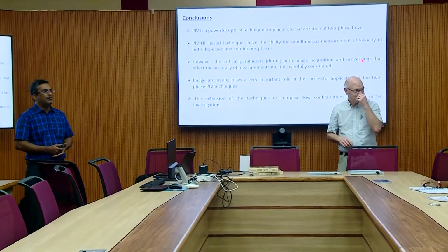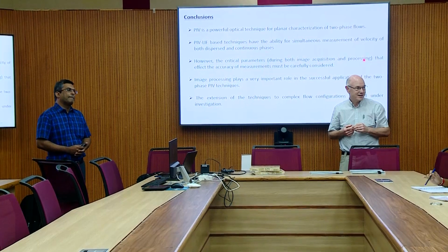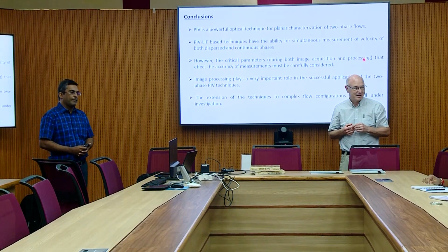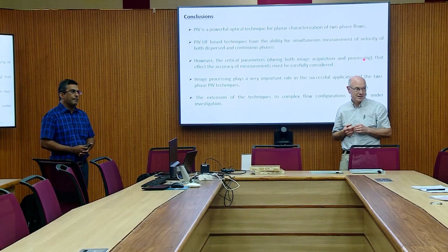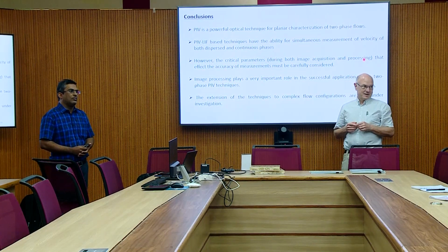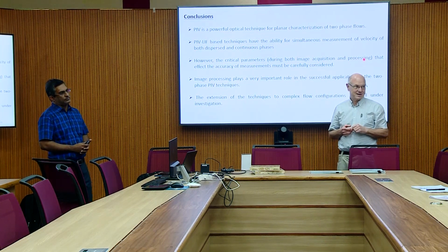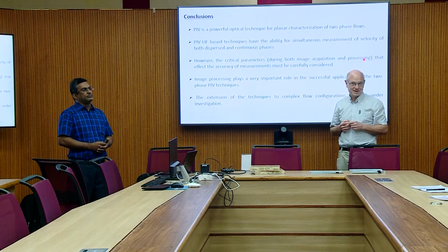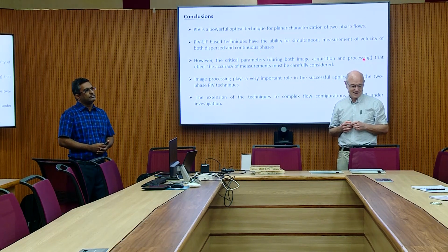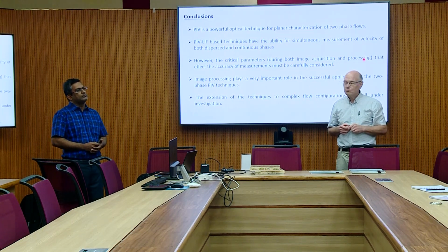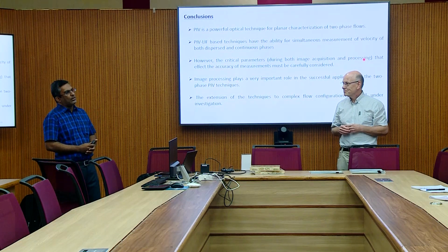Okay, I have one question. You discussed statistical convergence when we are going to higher orders of detail in the flow. So how do we study that convergence? If we are taking images over some particular time, and we reduce that imaging time, meaning we are increasing the FPS and taking more images in that time, how do we understand that statistical convergence is reached?